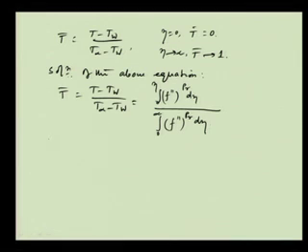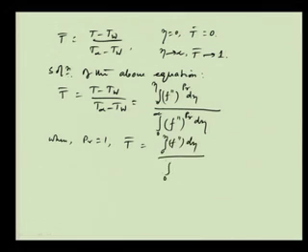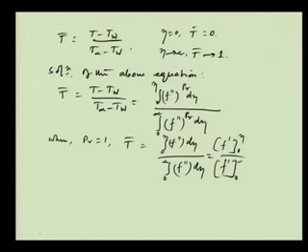And interestingly, when Prandtl is equal to 1, then T̄ becomes integral 0 to η of f double dash dη by integral 0 to infinity of f double dash dη, and that is equal to f dash from 0 to η by f dash from 0 to infinity, since the derivative of f double dash is f dash, and this is equal to f dash η, which is equal to Vx by V∞.